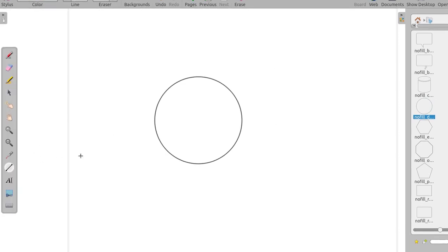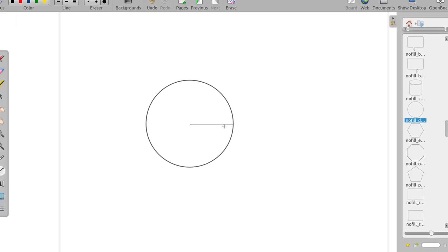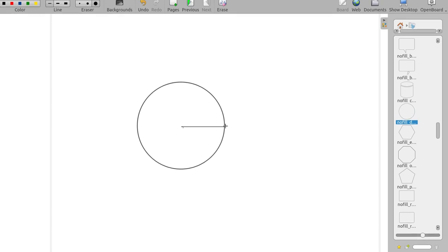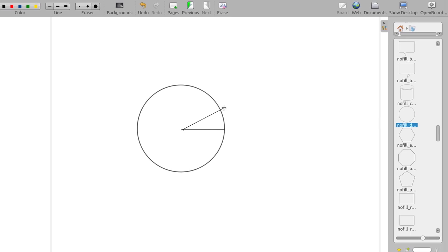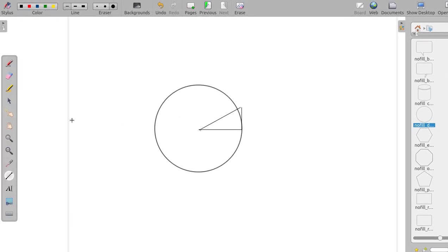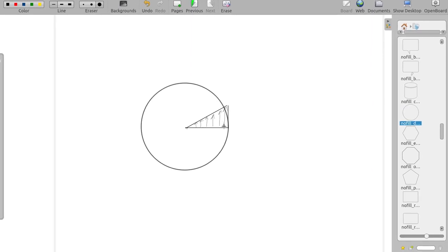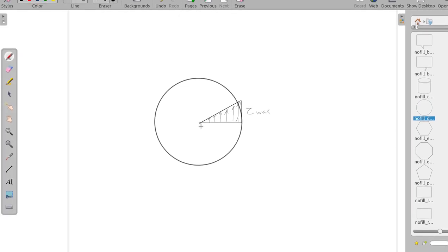Now we have already assumed that shear strain is varying linearly from central axis to outer surface. So shear stress is also varying from 0 to maximum, from central axis to outer surface. So this maximum value here, we will call it tau max.